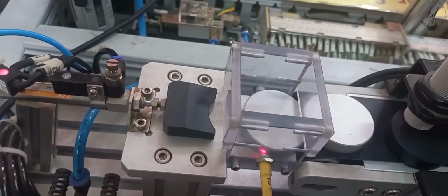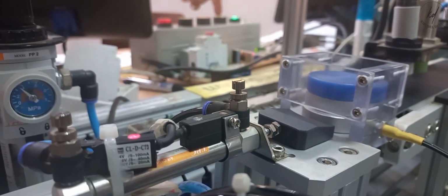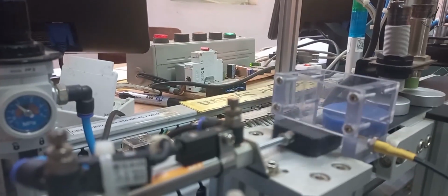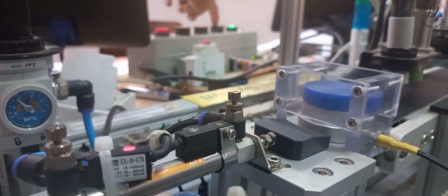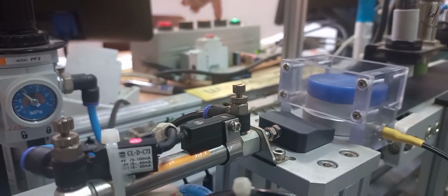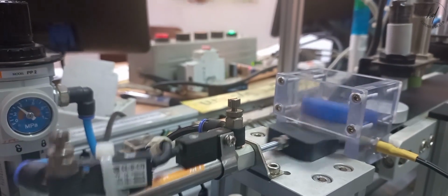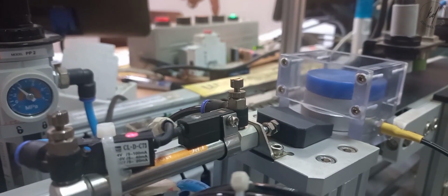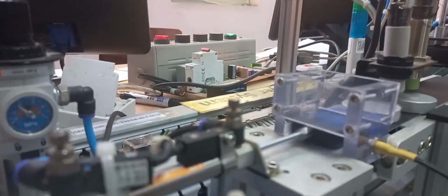By modifying the ladder diagram of the above, here the up counter is used and executes the task, that is, as the push button is pressed the supply cylinder advances and returns 3 times. After all, the supply cylinder stays in the retracted position as long as the push button is not pressed again.